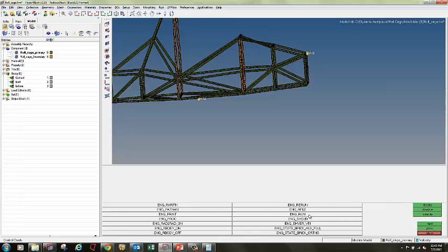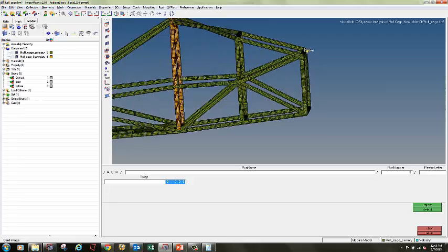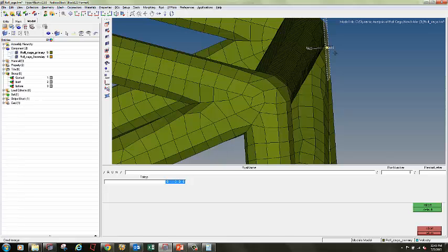The first card is engine run. Enter the value as t-stop. Here t-stop means for how much time you want to solve your model, how long you want the solver to run to get the results. So how can you decide it? We have the velocity as 16,666 millimeters per second.